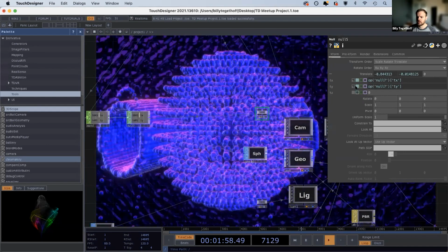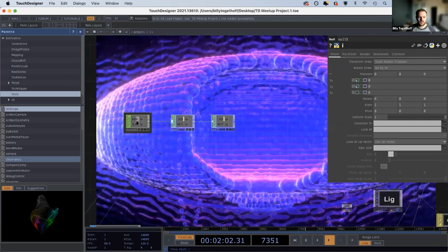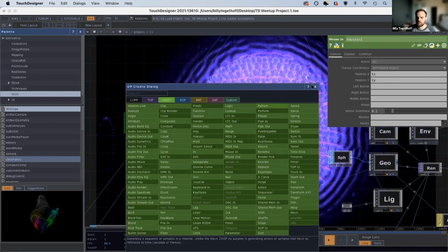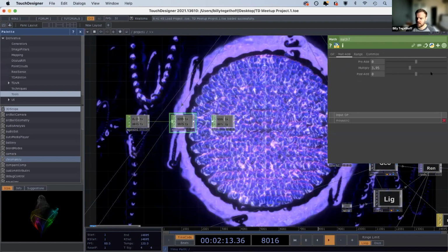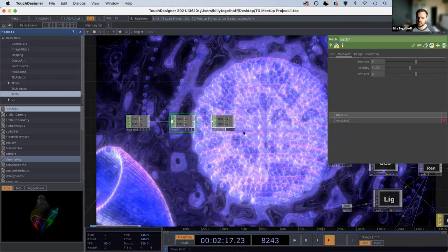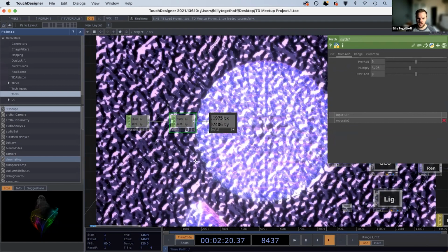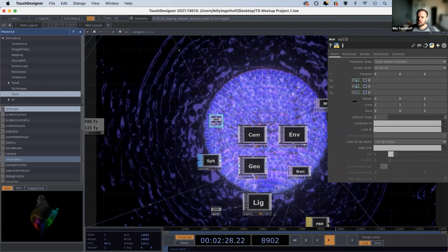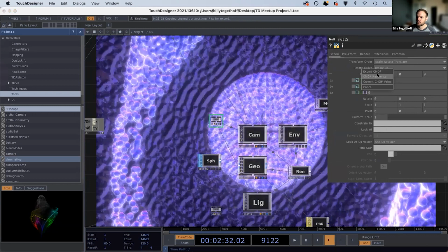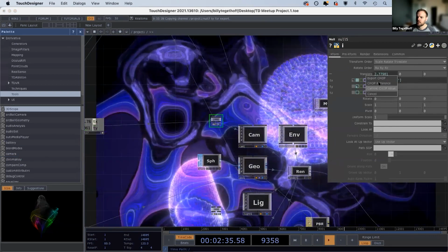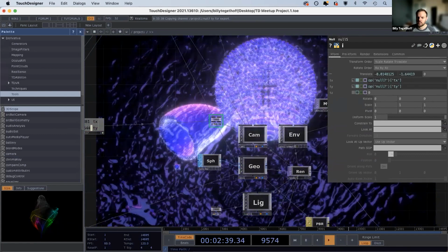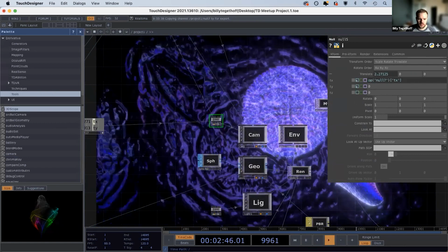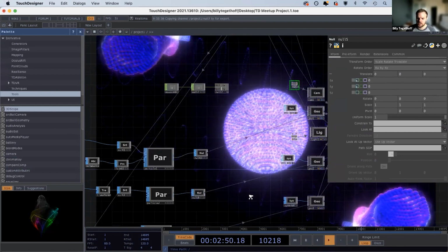Just to cover how I did that real quick, if you grab a mouse in chop from your menu here, wherever it is, there it is, bang it out to a null and then add a math to adjust the range depending on how drastic you want your movements to be. You can then just activate the viewer there and drag your TX value onto, not the camera, onto your look at in here, select chop reference, and then do the same thing with Y. And there you go. We have some slightly more interesting camera movements depending on what kind of aesthetic you're going for. So anyway, just want to talk about that real quick before we talk about the rest of the 3D stuff going on here.